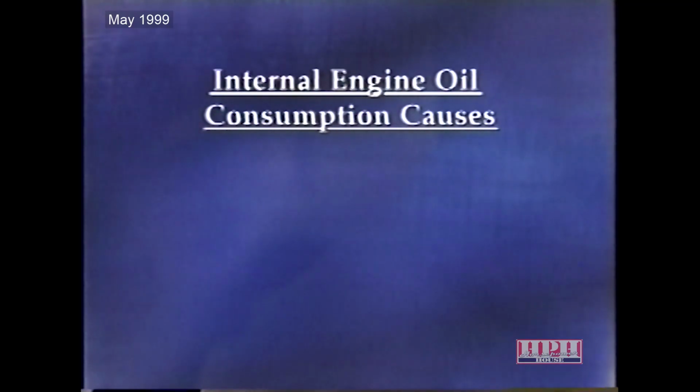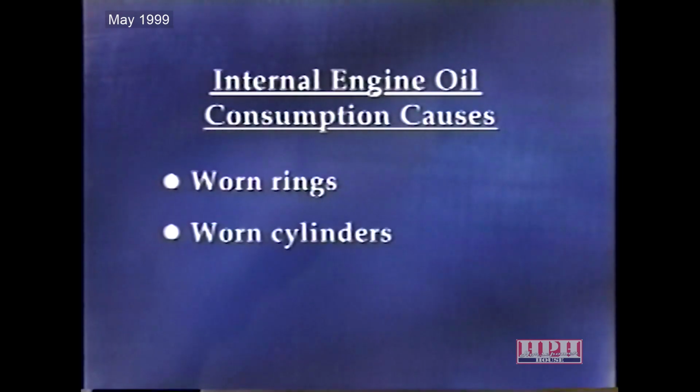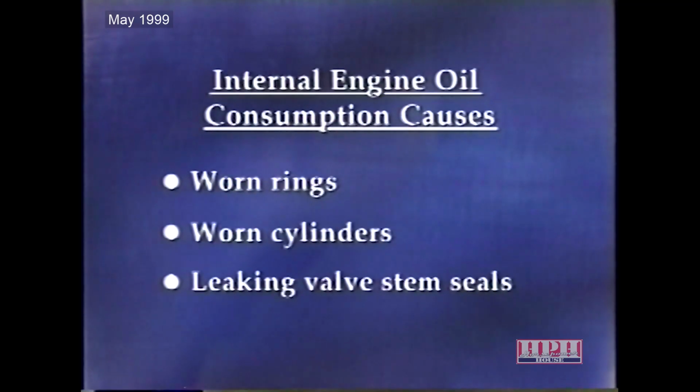Internal oil consumption can occur as a result of oil entering the combustion chambers. Some possible causes of this are worn rings, worn cylinders, or leaking valve stem seals.